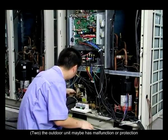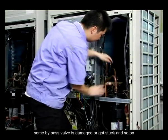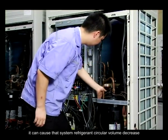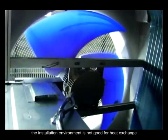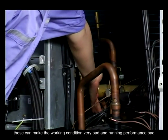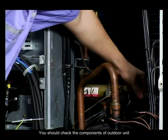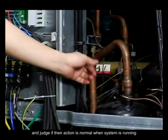2. The outdoor unit may have a malfunction or protection. Some bypass valve is damaged or stuck and so on, which can decrease the system refrigerant circulation volume. The outdoor unit air return is short circuited or the installation environment is not good for heat exchange. Outdoor fan air volume is small. These can make the working condition very bad and the running performance bad. You should check the components of the outdoor unit and judge if their action is normal when the system is running.